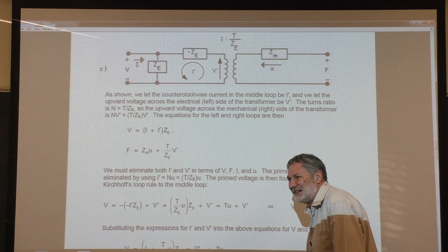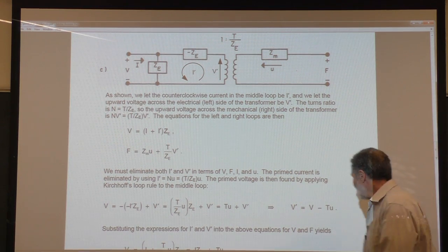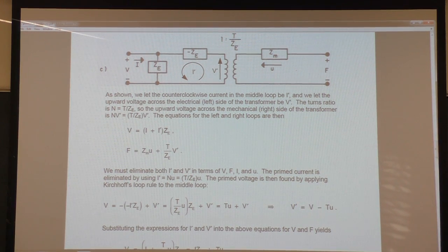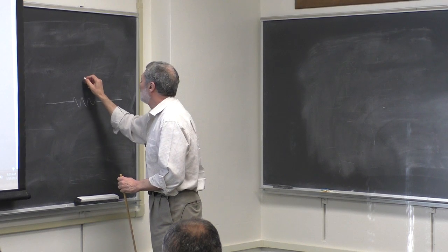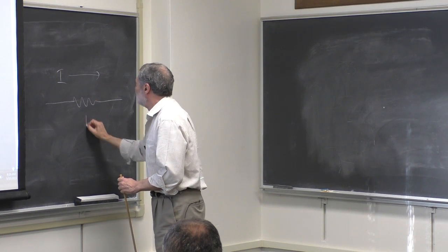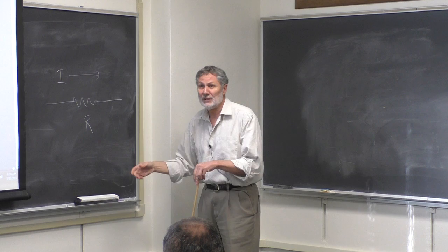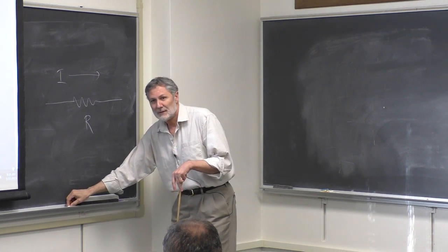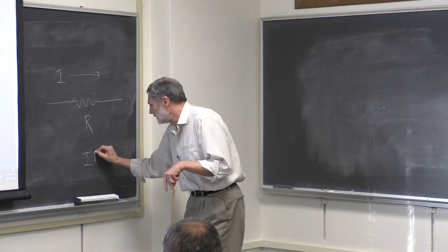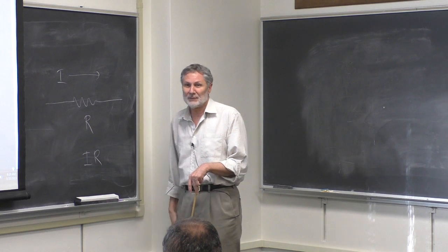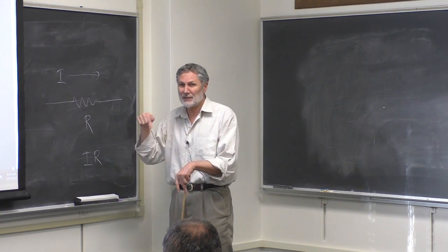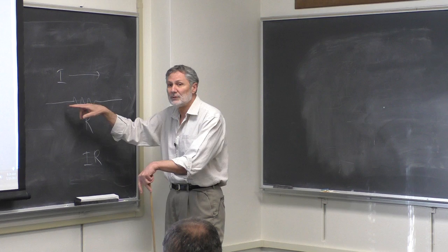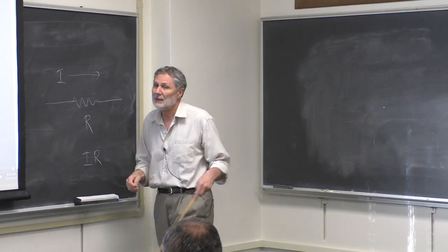then the drop is positive. Okay. Right, when we go across a resistor, I've got a current in this resistor. What's the voltage drop? It's I times R. It's not minus, it is the drop. The negative is in the drop. The voltage decreases by IR.